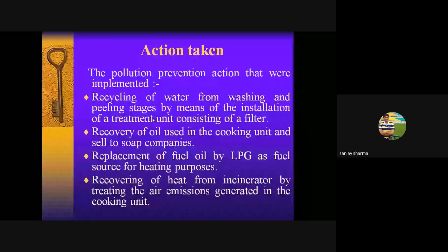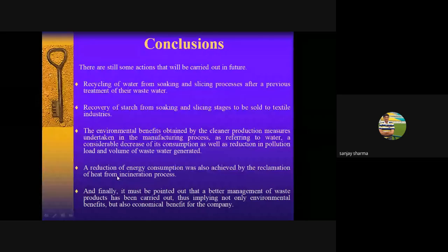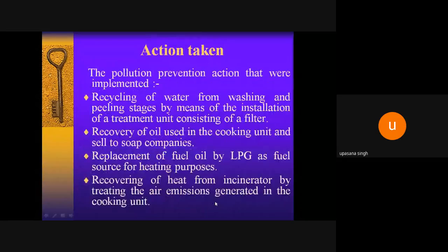Reduction of the energy consumption was achieved by the reclamation of heat from the incineration process. And finally, it must be pointed out that better management of waste products has been carried out, implying not only environmental benefits but also economic benefits for the company. So actions taken: recycling of water from washing and peeling stages by means of installation of a treatment unit consisting of a filter, recovery of oil used in the cooking unit and sale to the soap companies, replacement of